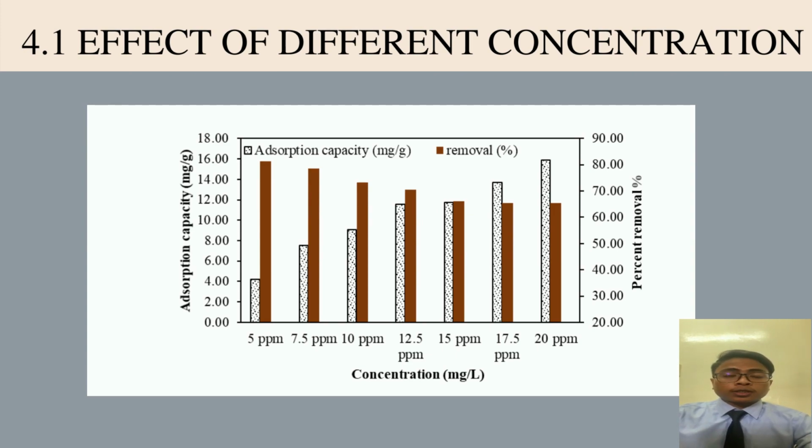As the initial concentration was raised to 20 mg per liter, activated carbon's loading capacity was raised to 269.52 mg per gram, and the removal percentage was decreased from 59 to 15%. It is because of the increased affinity of the interaction groups on the activated carbon surface, which speeds up carbofuran adsorption.